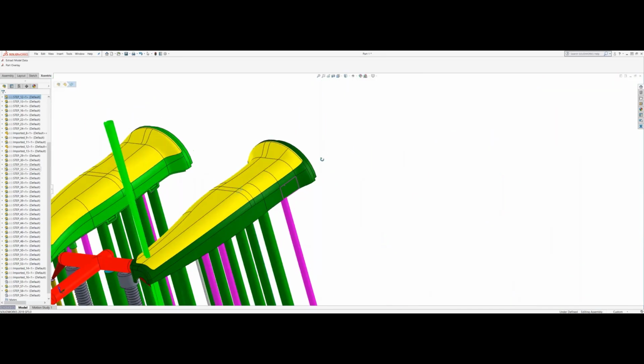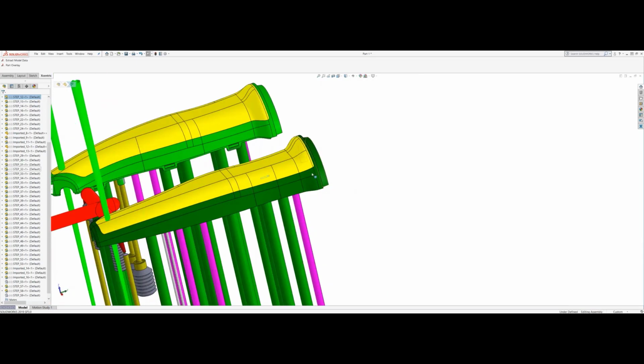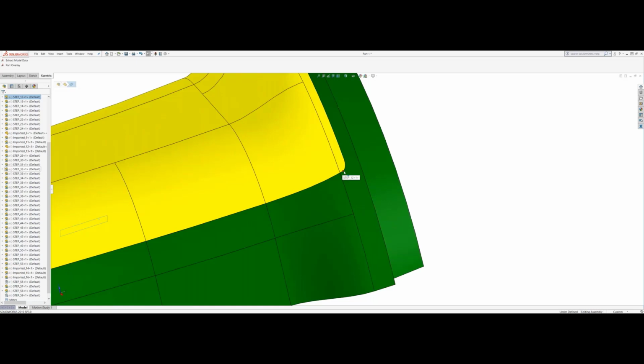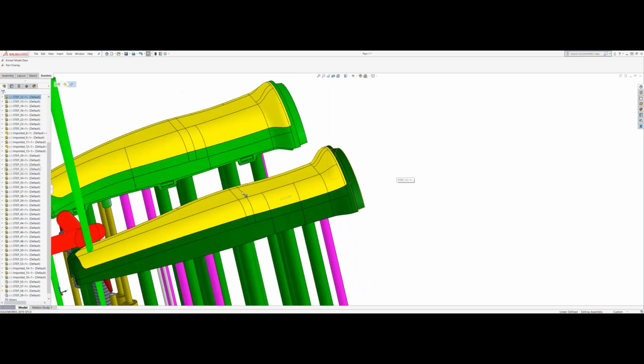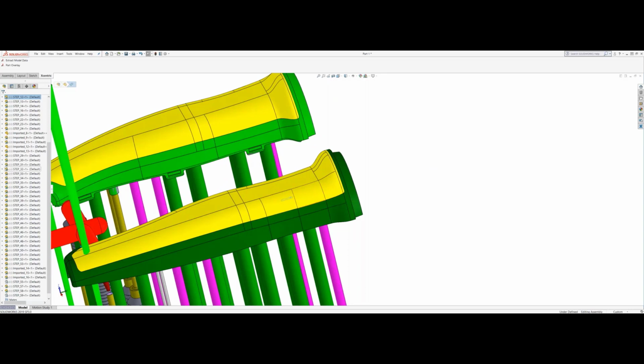So the challenging thing with this one, as Glenn mentioned, was this seamless handoff or transition between the overmold and the substrate. As we all know, material has a shrink rate. Rubber materials more so than others, and filling this part and getting this material to shut off tight and clean against these edges, against a substrate that is going to have some variance to it. So it was really tight tolerance on the substrates, fitting that to the overmold tool, and getting a nice clean part